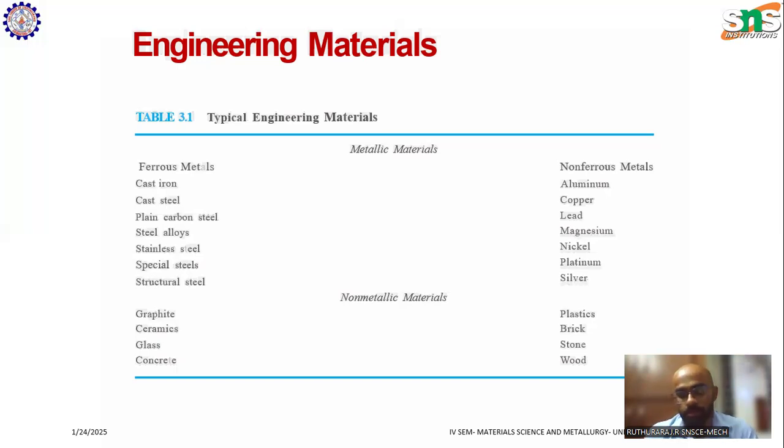There is another type of deformation, which is called plastic deformation. It is an evolved form of elastic deformation. Take the same rubber band, and imagine you are applying a very high amount of tensile load, that is, you are stretching it beyond its elastic limit. Once you release it, it will not get back to its original shape. It will be in a somewhat stretched form. That type of deformation cannot be undone, so it cannot return to its original shape.